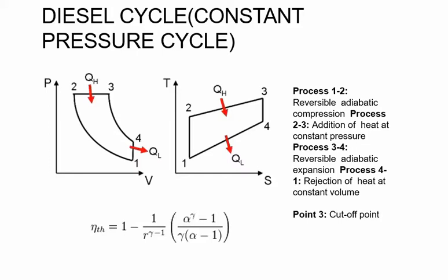The summation of many such cycles per unit of time is called the developed power. The W out is also called the gross work, some of which is used in the next cycle of the engine to compress the next charge.